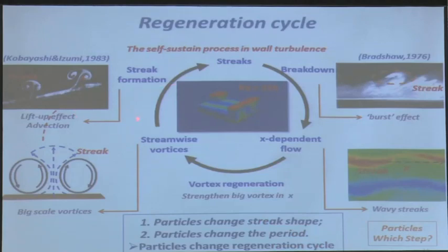And last slide, just to explain why it is very complex. It's because the onset of turbulence is very progressive. Actually, it's not like the flow is becoming turbulent everywhere like that. Actually, it is becoming turbulent from very subtle instabilities close to the wall. And for now, we don't know how the particles are going to modify these instabilities, which are leading to the onset of turbulence. So we do experiments, we do simulations with pipe flows, with channel flows, with shear flows, trying to understand what is the interplay between the particles and the turbulent flow.